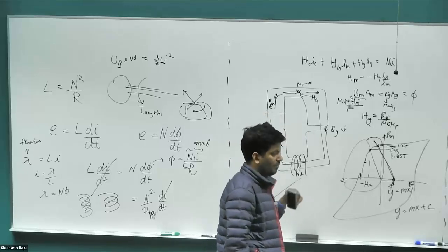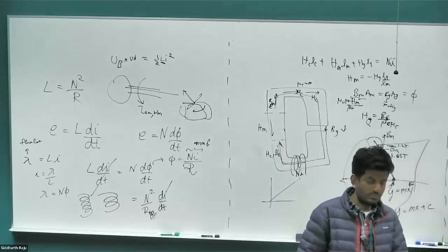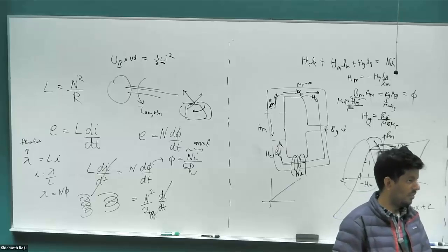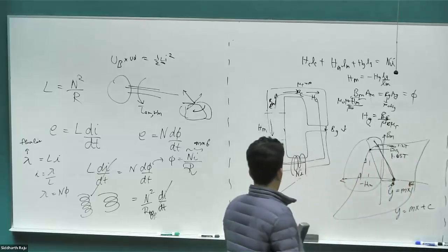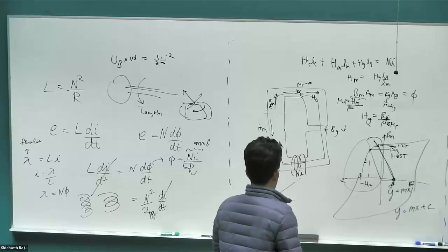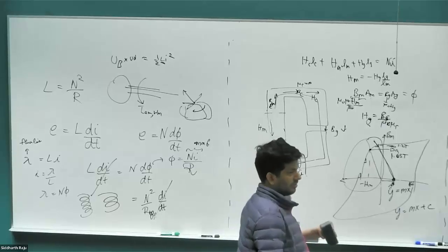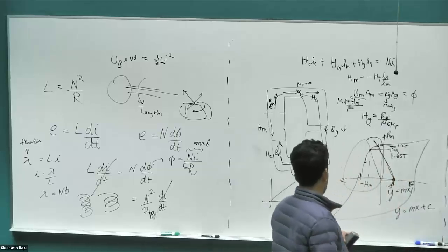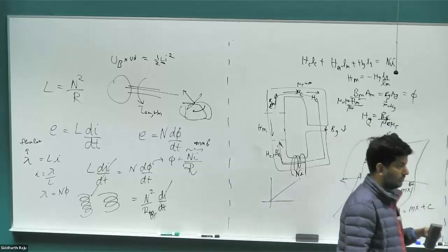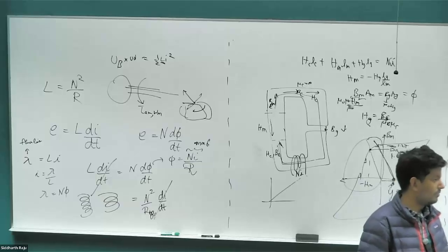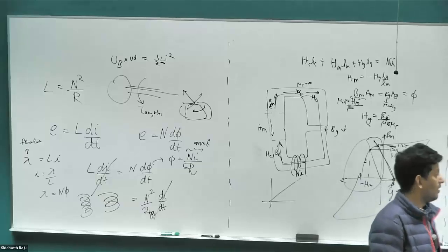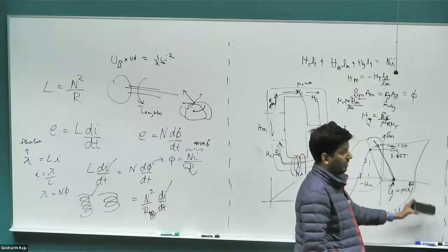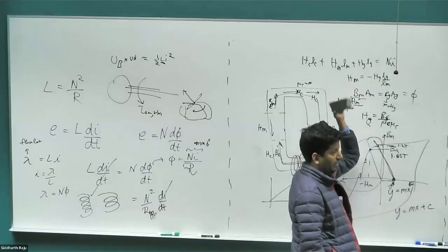Got it. Thank you. One more time, to find the load line, you just say B_m equals some value times H_m, basically. And then that's your line. And why does the load line shift over again? It's just constant. Yeah, so this expression, right? Then Ni will just show up as a constant times L_c by A_g, some other terms.